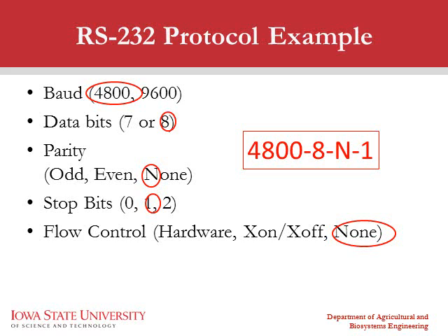And so in the manual of a GPS receiver or device, you may very well see this notation, where the 8N1 typically doesn't change for GPS receivers, but the 4800 will absolutely change depending on the speed at which the receiver is set to. And likewise, you're often able to change this baud rate through the Precision Ag display to set up your receiver to send at a different rate.